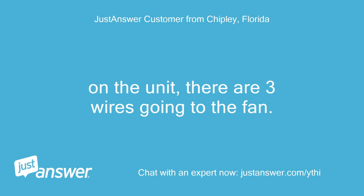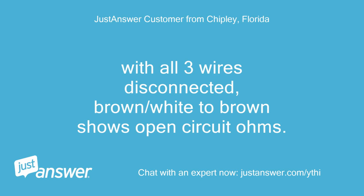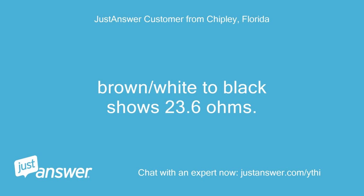On the unit, there are 3 wires going to the fan. Brown/white, brown, black. With all three wires disconnected, brown/white to brown shows open circuit ohms. Brown/white to black shows 23.6 ohms.